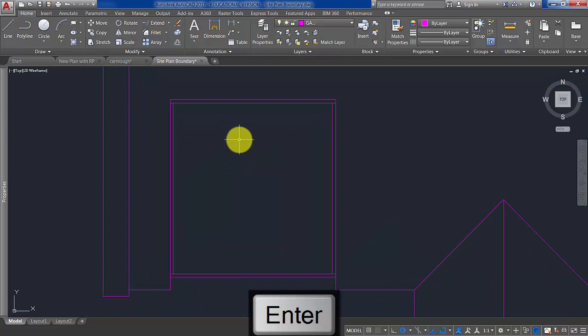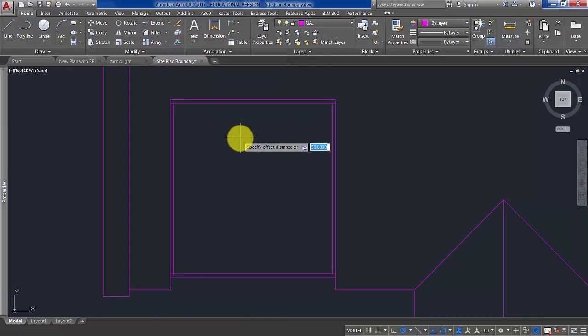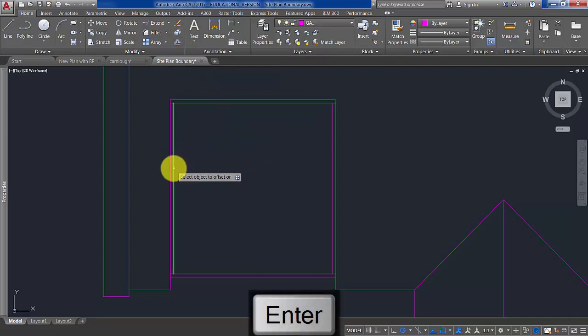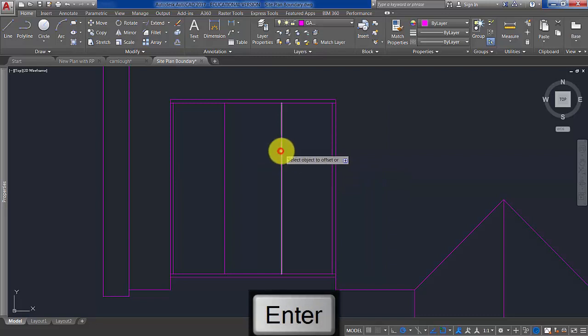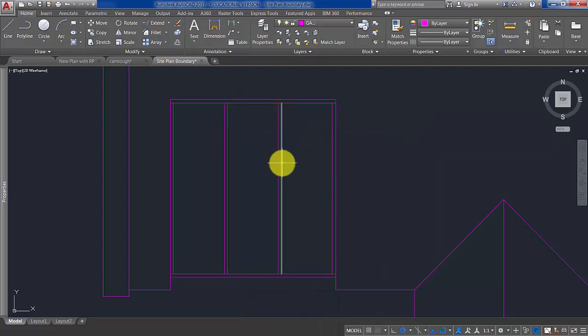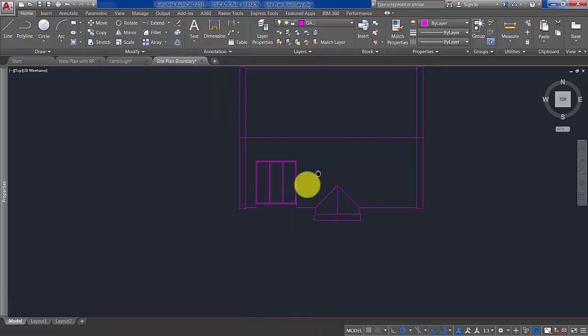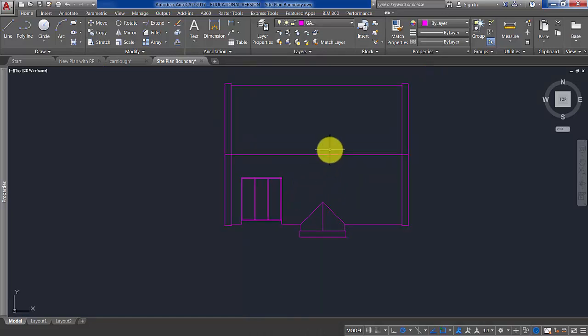And then if we work out where the other parts of the frame are, it's equidistant, so offset by 800 from both sides, and then 50 to get the next element of the frame, and then we can just do a distance check there, in between is 800. Okay, so that's all the elements of the roof showing. We just need to try and indicate in some way what finish that has.